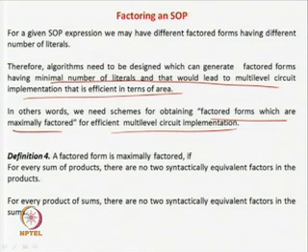So, we require algorithms, which we will be studying now, that can take a minimized SOP form and factorize it maximally, so that the number of literals and terms in it will be as small as possible, and the implementation is area efficient.